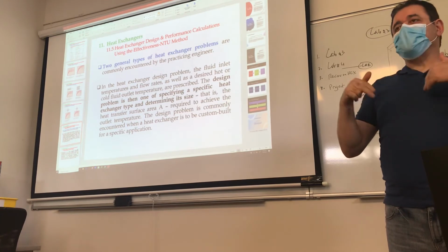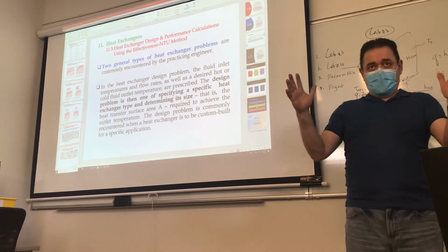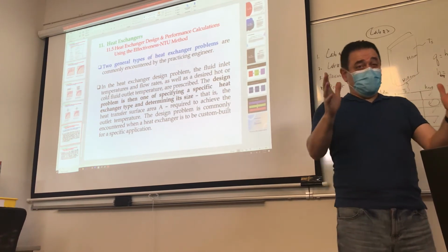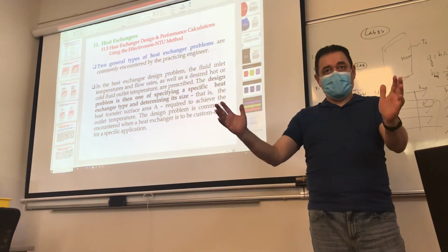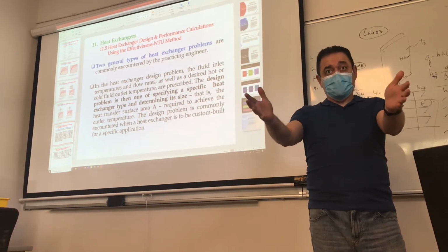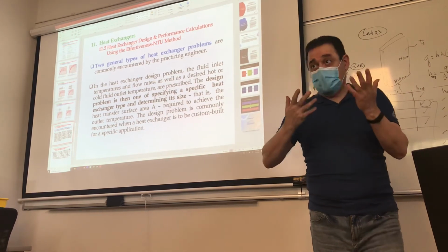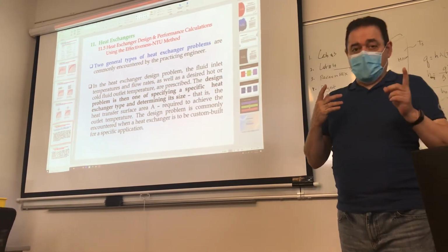Analyzing, which is called the performance analysis, is when you are given a heat exchanger, and you are doing an analysis to see if there is a process or a heat exchange that you want to achieve. Can the thing that you were supplied with do it? So you're not designing in that case, you're just analyzing.